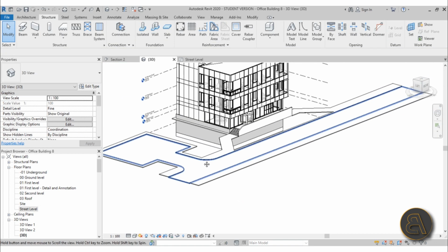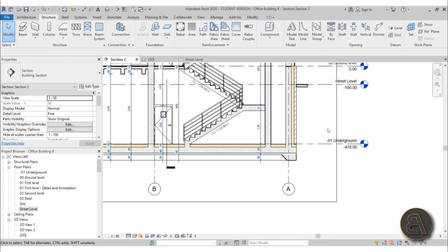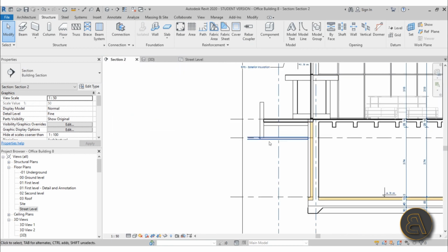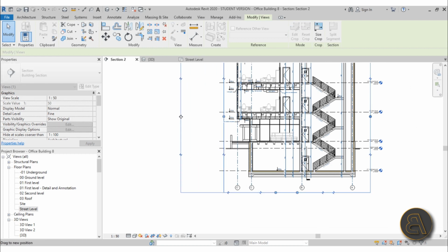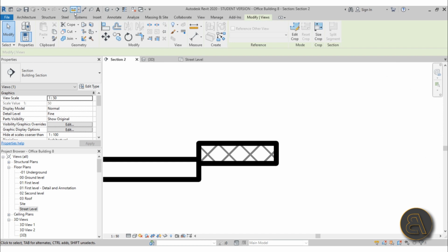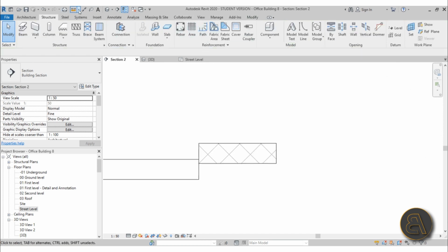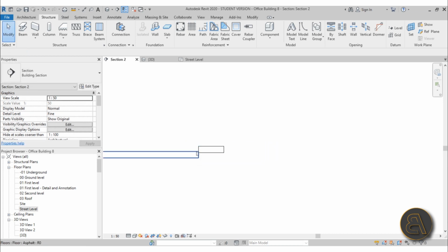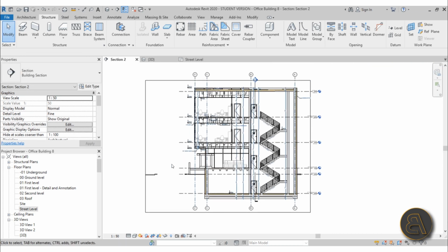Okay, so to see what that would look like, let's go here into the section view, and here maybe extend this section view a little bit. Just like that. There we go. So here you can measure this height. Now I already know the height, but let's just measure it to double check. And yeah, it's 8 centimeters. So we need an 8 centimeter curb for something like this.